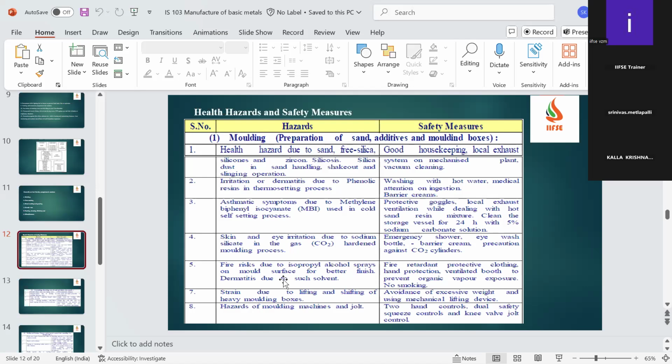It is nothing but a fine layer over the mold. It is just a kind of skin over the mold so that the sand inclusion will not happen. Sand inclusion is nothing but, while pouring a metal, because of that hot condition, the sand which is there on the surface should not be included in my part.